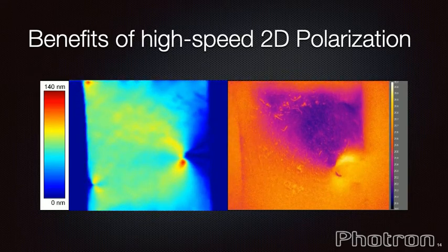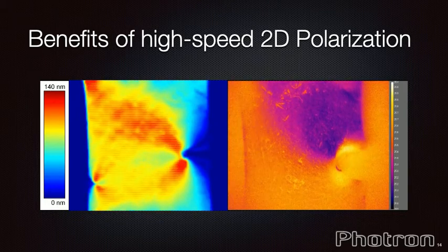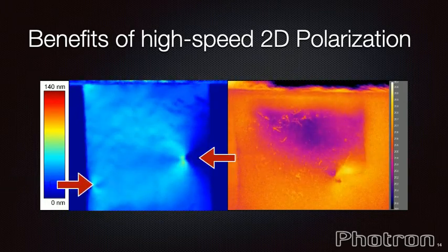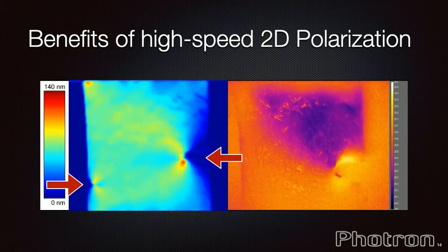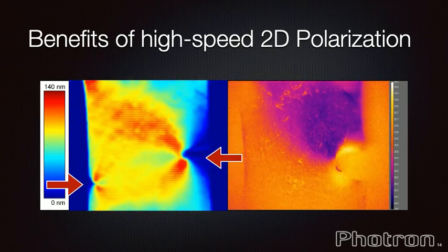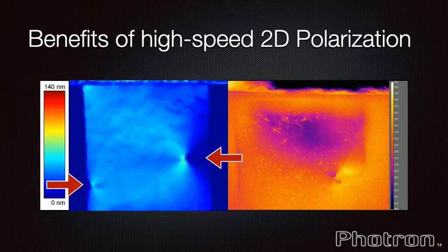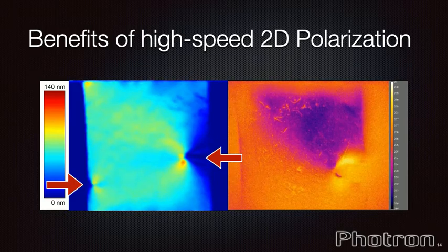Here again, the polarization shows internal stress, this time in a film stretch test recorded at 120 frames per second. Note how the retardation image best shows the stress around the two nicks that is not visible in the IR view and enables us to analyze how stress is distributed around and contributes to the fractures.